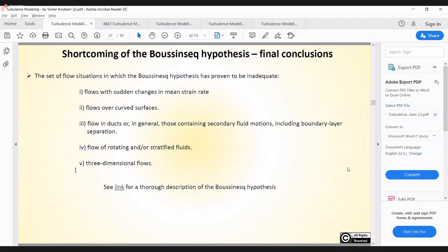By 3-dimensional flows, I mean if you have a building with a straight roof, then you have separation, and what happens inside the separation is totally unrealizable with a RANS model. You need to have turbulent content to imagine what happens there.